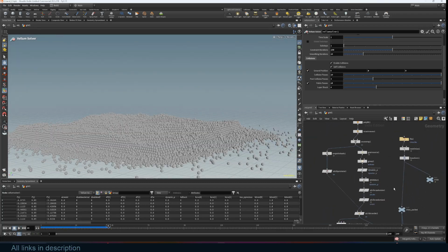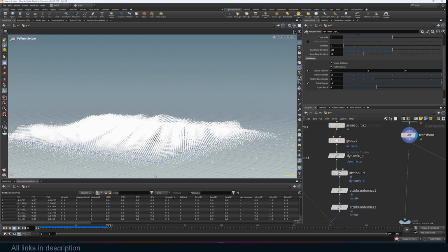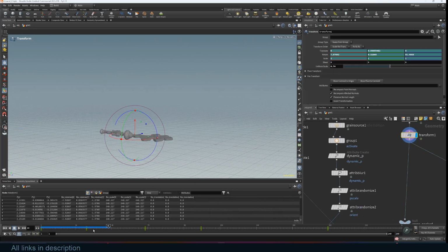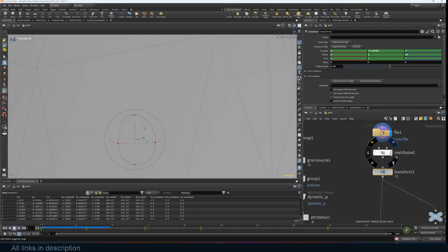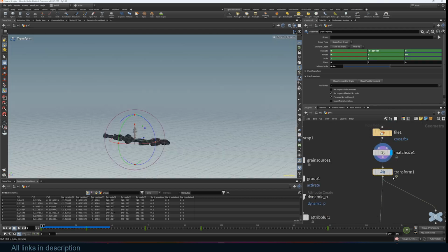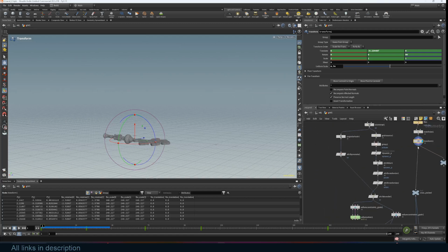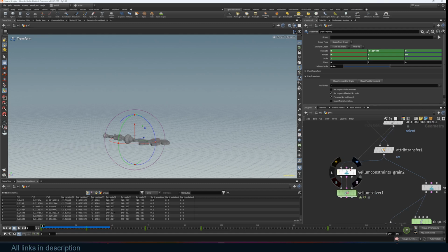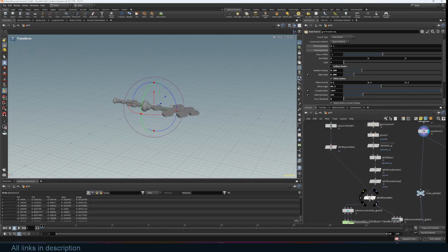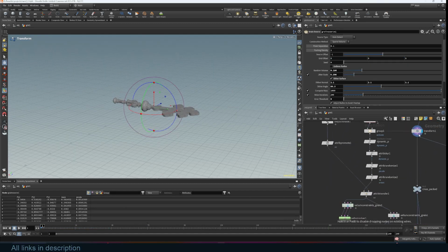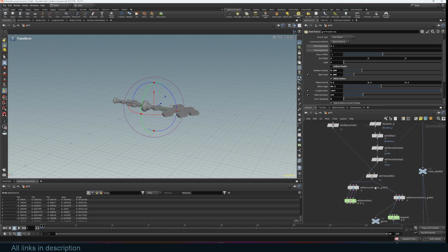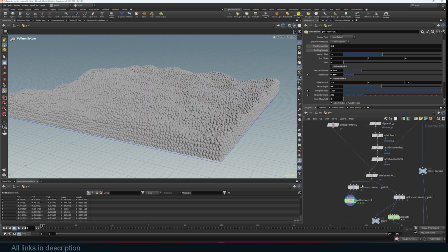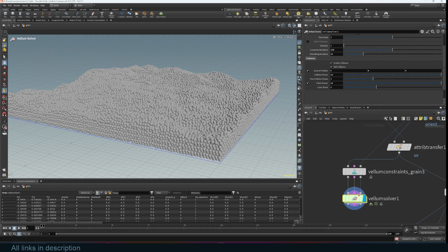If you animate an object, for example, I animated this cross moving from the ground up like that. I imported it. It was too big. I resized it using this smart size, and then animated it with some keyframes. And if you drag this into the Vellum collision node, so Vellum has these inputs, all you have to do to turn it into a collider, just wire that directly into the collisions. It becomes a collider, and with those two nodes, you are already done.